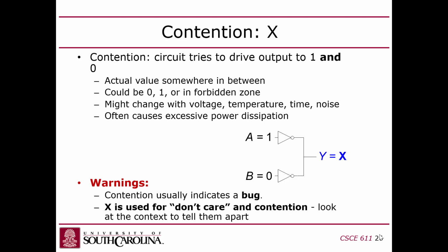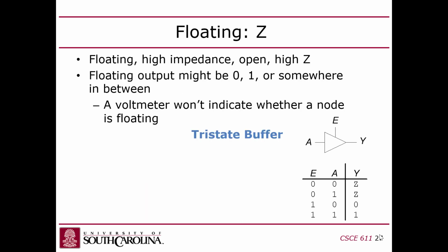No, you could. You could have two assignment statements that both connect to the same output, but you'll get an error when you go to compile it, right? When you go to synthesize it, you'll get an error. If you're simulating it, you'll get an X in the simulation window. So if you see an X, that usually means you're double driving something. I think that's everything that's in that slide.